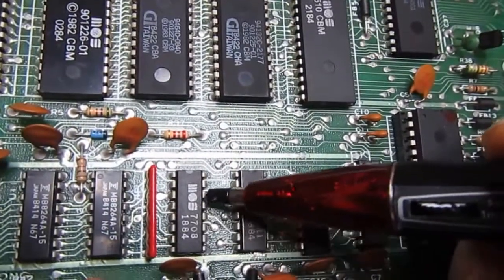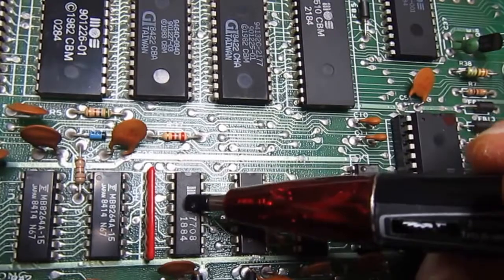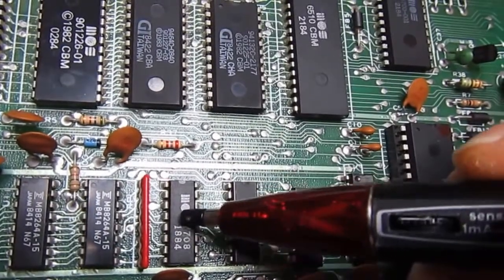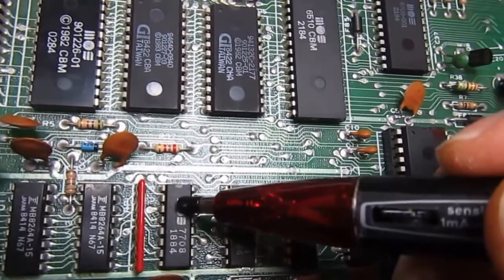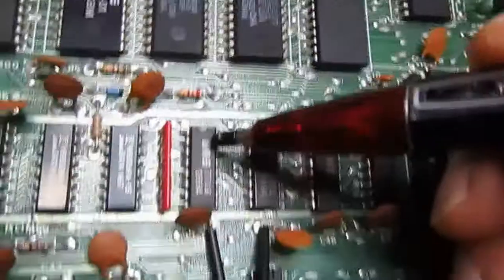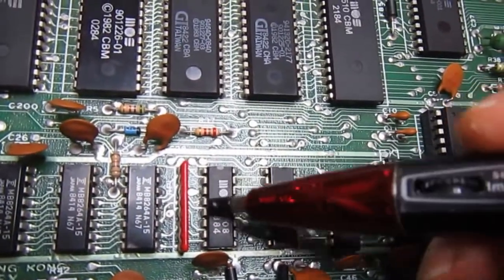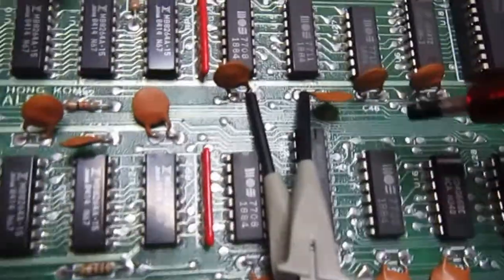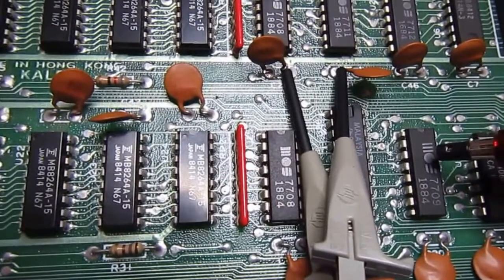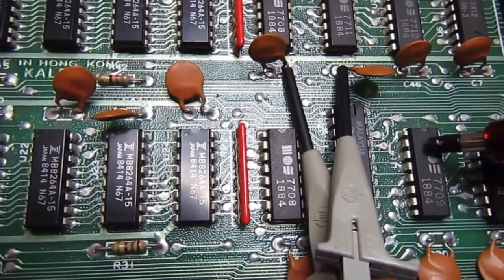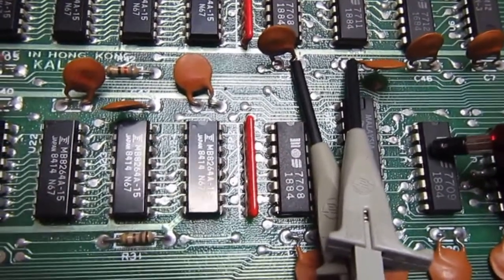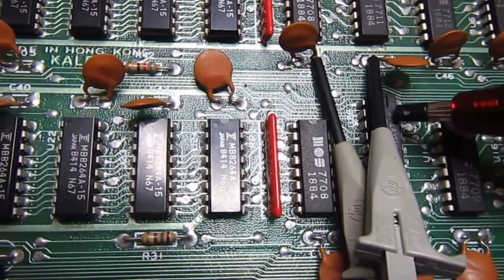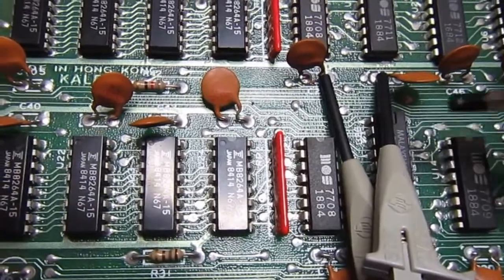Okay, I found that this chip has two probably shorted outputs, not inside itself maybe, but on what it is driving. The pin 4 and pin 7, among the other things, drive this chip on pin 4 and this one on pin 18.